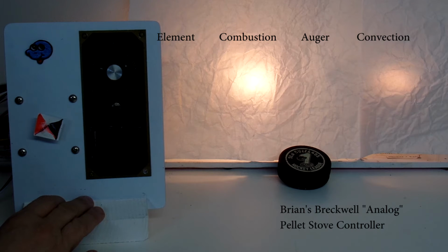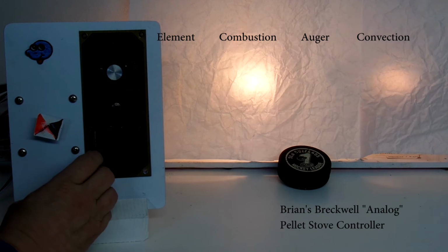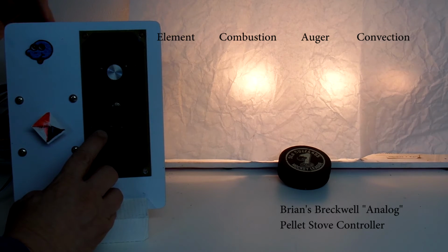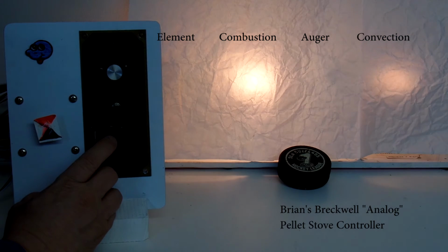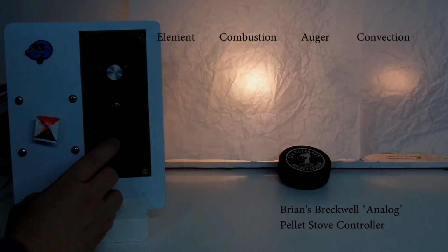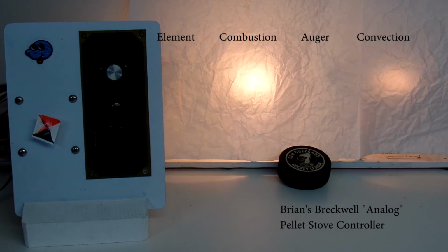The last thing I can do in manual mode is to check the auger drive. To do that, press the manual feed button, which is a momentary switch, and we notice that the light bulb for the auger came on. We hear the motor spinning, and we see the decal spinning as well. Release, press. So that's functioning correctly. So that's all the manual functions of the controller. Everything seems normal so far.